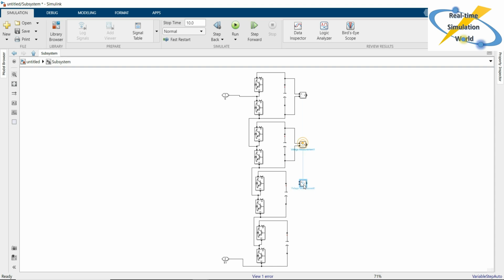because if you know why we are doing so, these capacitors will be charged and discharged simultaneously. So if the grid current is positive or negative, we then have to simultaneously charge and discharge these capacitors. We also have to sort them, like the capacitor which is fully charged, we have to insert those submodules during the operation of MMC, right? So yeah, this is needed.